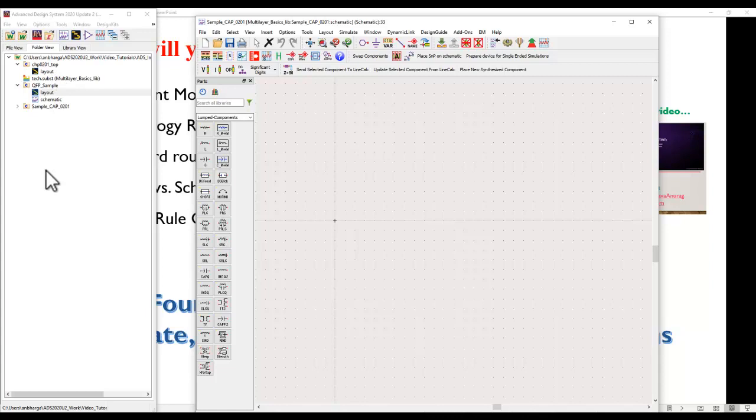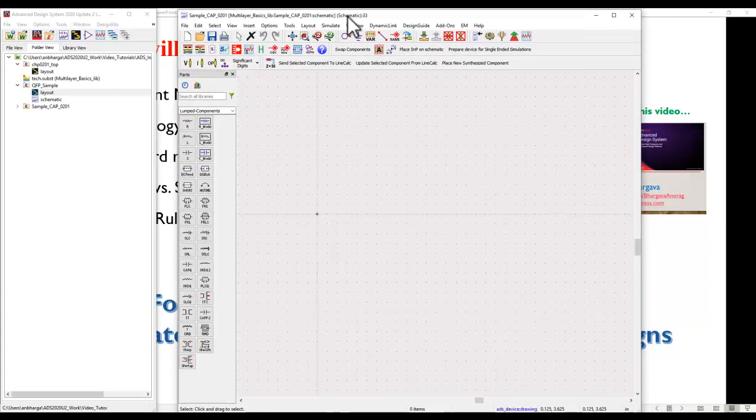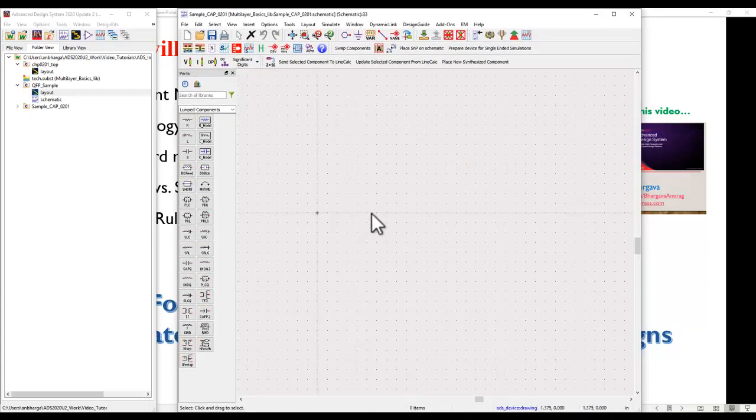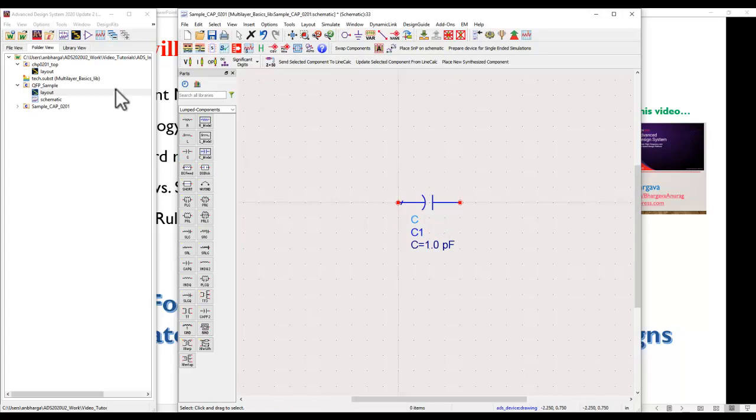I don't need to do this footprint modeling 3 times. I can do just one layout and then use that layout in all the components where I need it. Now let's see how we can create this kind of parametric component here. So for example, I'm going to take a capacitor, and now for this capacitor, I will need to associate that footprint.